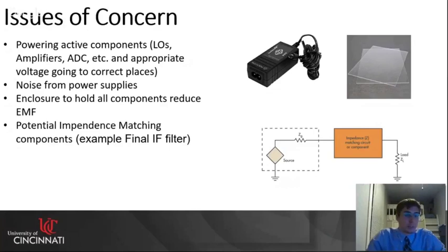While our project has proceeded smoothly so far this semester during the design phase, there are some outstanding issues of concern that we'd like to address and research for next semester. One of these main issues of concern is how we're going to power active components in our circuit, such as the local oscillators, amplifiers, and ADC. These different active components need different voltage levels to power them, and we need to design a power supply circuit that can provide these voltages to these components. Also, we are concerned that the noise from the power supply might negatively affect the performance of our spectrum analyzer, given that we're using such high frequency sensitive components.